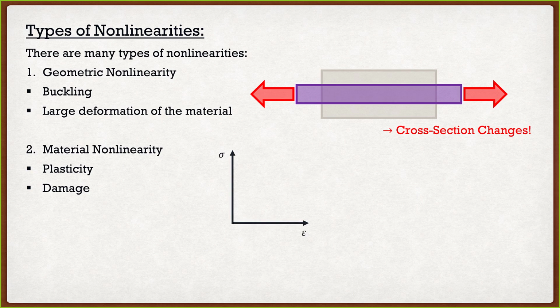Now, up until this point, when we're dealing with the stress-strain curve, we assumed that things were nice and elastic. Now, if this was steel right here, again, this is probably pretty fine for most everyday scenarios. In typical everyday scenarios, we're not actually yielding our steel or anything like that. But it's something that we have to take into account, that if we had a catastrophic event or something crazy like an earthquake, our steel will probably yield. And our material behavior can't just be defined by this simple linear curve. It has to have that plastic portion after it yields. So this is going to be one of the things that we talk about next lecture. How do we incorporate that behavior into ABAQUS?